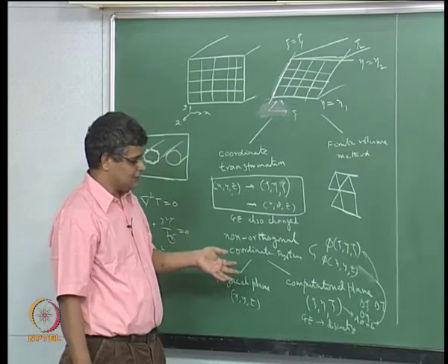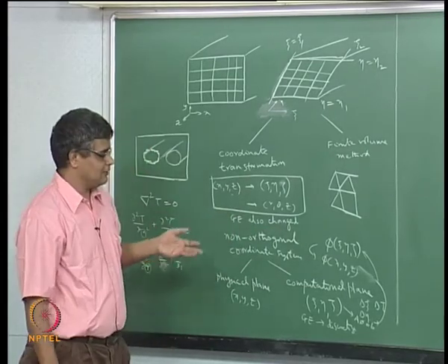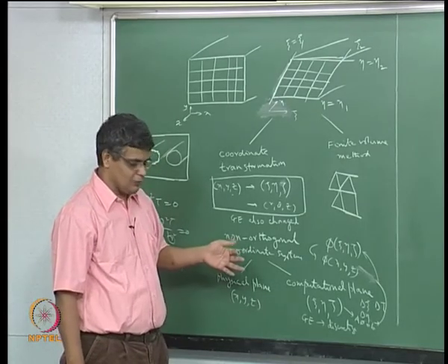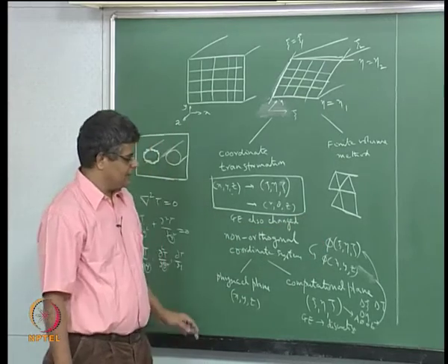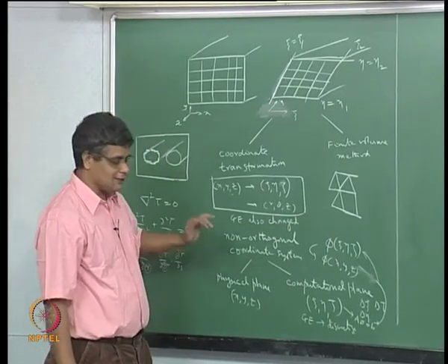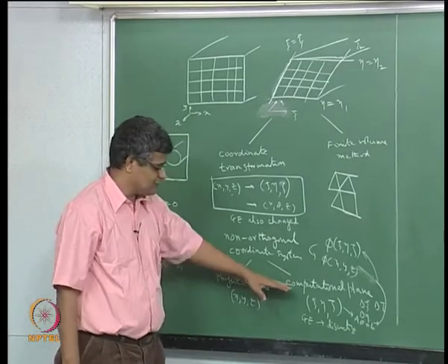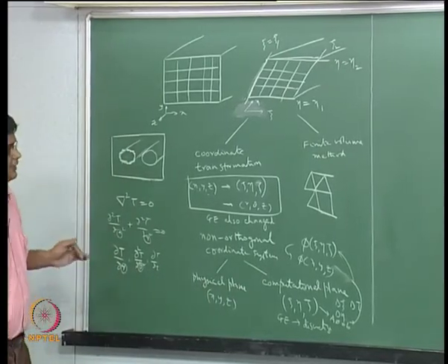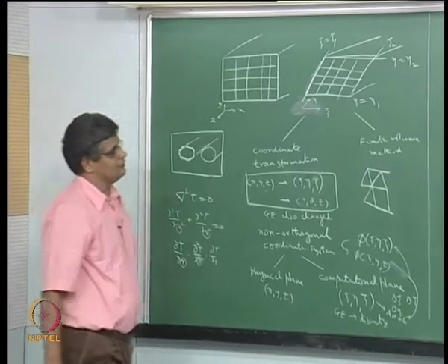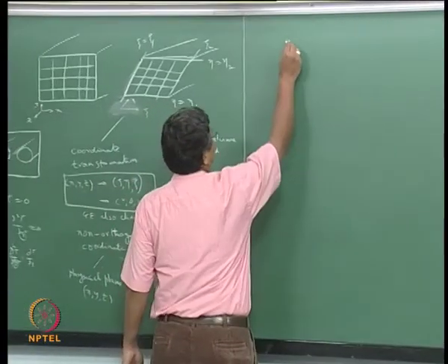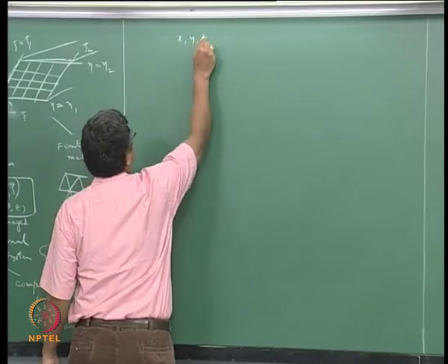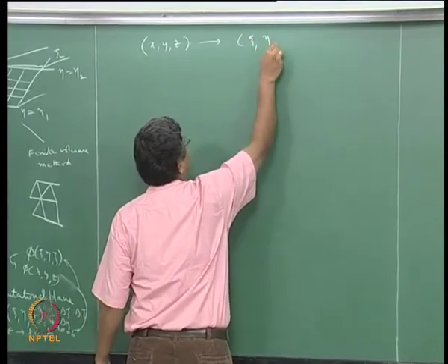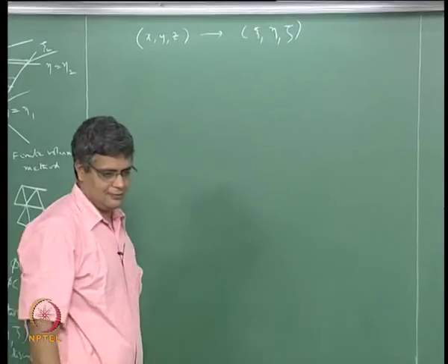We have several such matrix equations and we solve them using either Gauss-Seidel or multigrid, or whichever we think is the most appropriate, and then we get the solution here. So in this approach what we need to understand in addition is this transformation of physical and computational plane and transformation of the boundary conditions, and we will see what is involved in this process. First we will look at the transformation from xyz into psi, eta, zeta here.